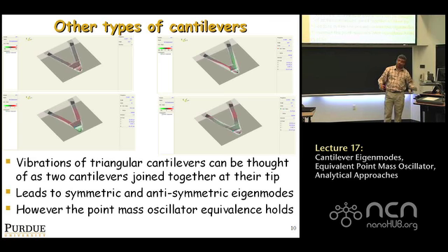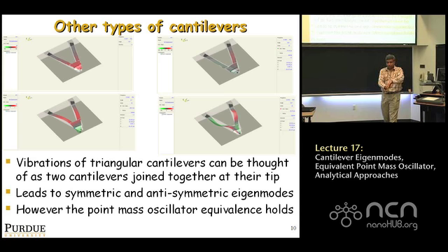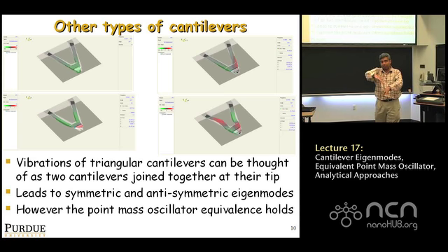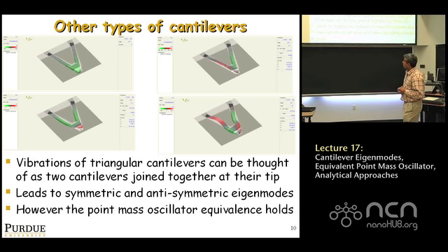Now you look at this one at the bottom left, and there's a second mode. And just like there's a second mode, there's an out of phase second mode. This is where both beams are oscillating in second mode, but out of phase, causing a twisting-like motion. And even this frequency is different. It's not the same frequency relationship as we had, okay?